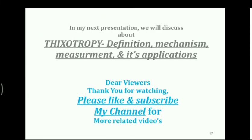So this is all about today's topic. In today's topic, we discussed the classification or types of flow, that is, Newtonian system and non-Newtonian system. Non-Newtonian systems are further classified into three types: plastic system, pseudoplastic system, and dilatant system. Plastic systems are also called Bingham bodies. Pseudoplastic systems are also called shear thinning systems, and the third type, dilatant systems, are also called shear thickening systems.